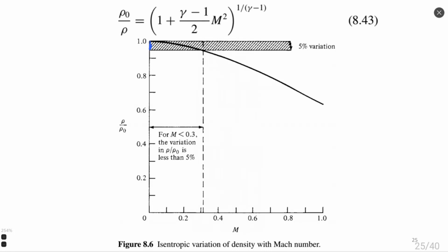In real life, any kind of flow is compressible. You already know this. Now we see numerically why it is actually 0.3: according to this function, when the Mach number is small, compressibility is small. When the Mach number increases beyond 0.3, we have a significant change of density, which cannot be ignored in our calculations.